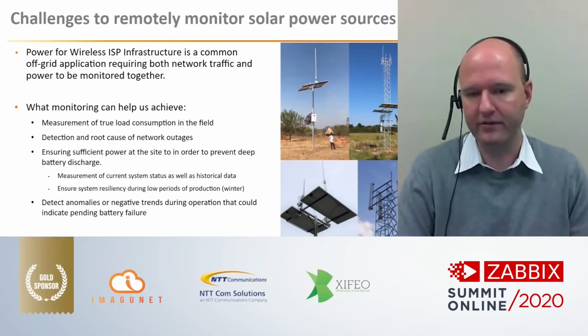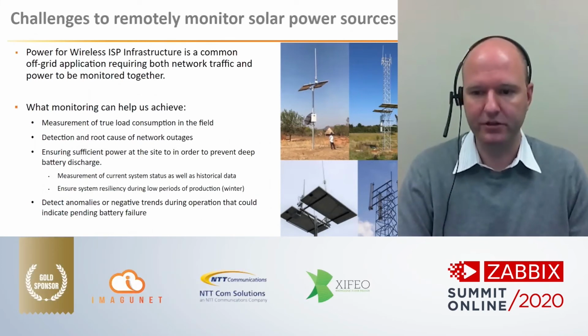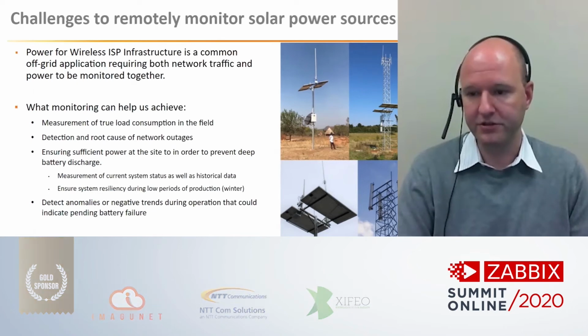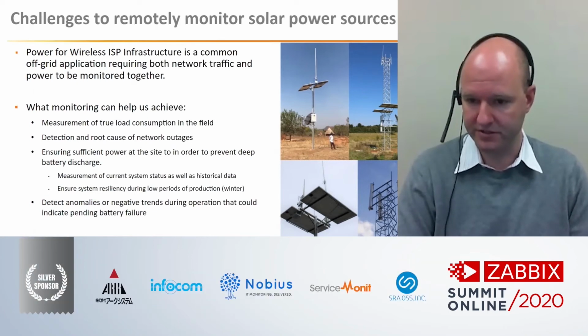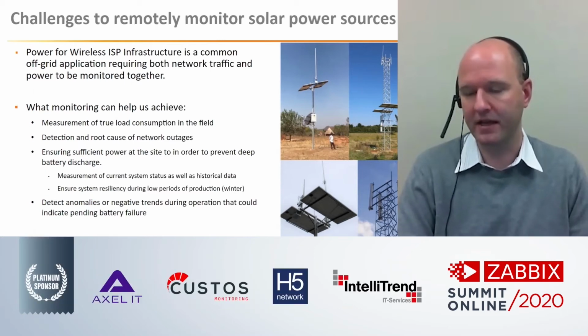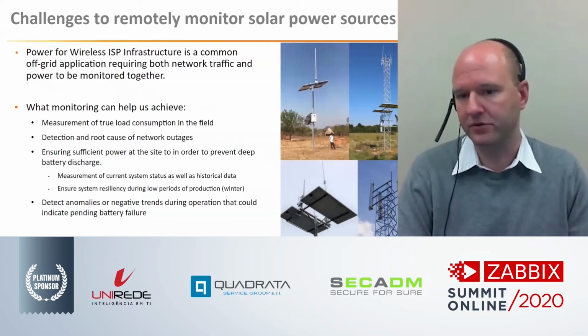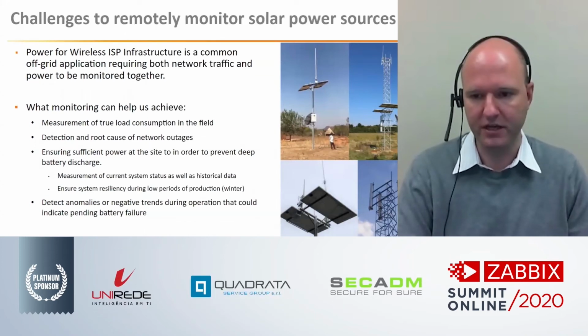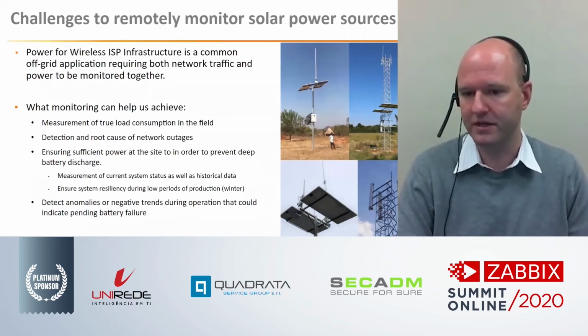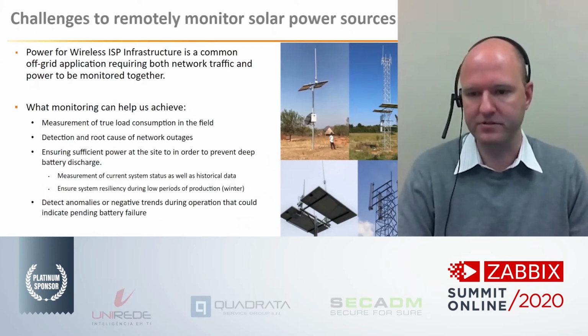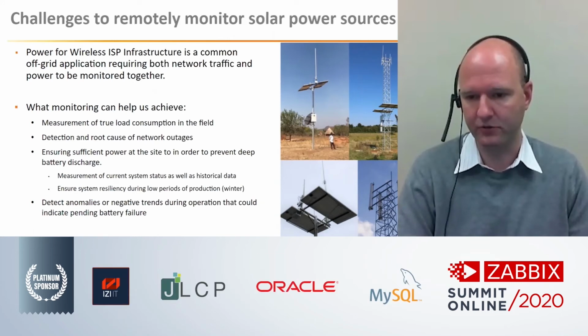So also, when you have long-term availability of data, you can look at month over month. You can compare season to season during similar power output periods of time, as well as look at trends and analyze the system's basically lifetime of operation. With a lot of lead acid batteries, a minimum of 5 years is generally acceptable. And with newer lithium technologies, we're seeing that extended to 10 or more years when adequately sized. So the batteries definitely can have a robust life as long as they are sized correctly and given adequate power.